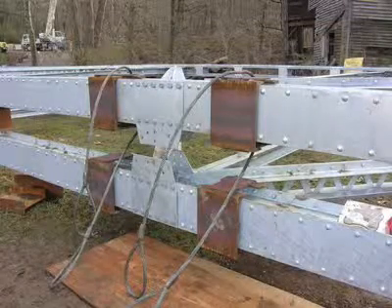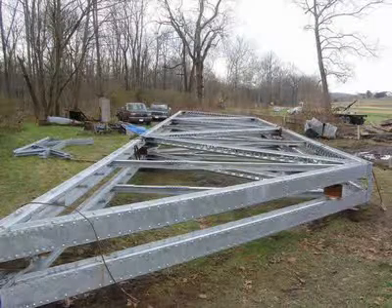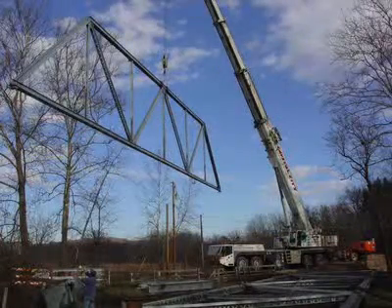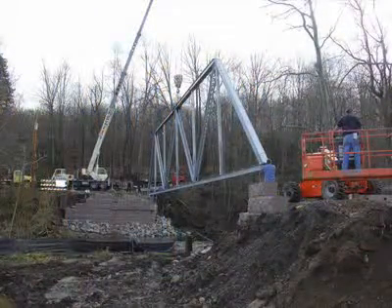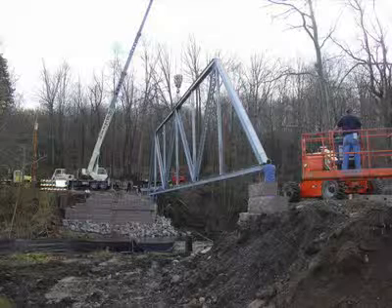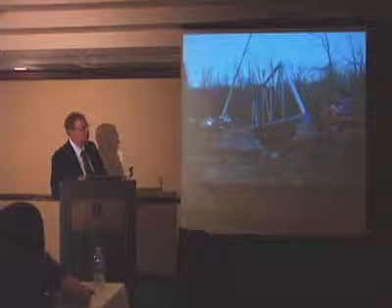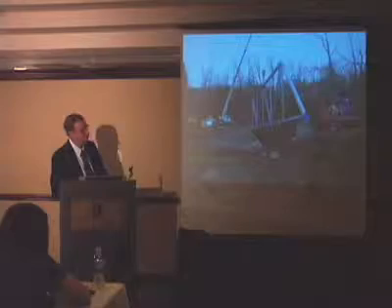The pieces were stacked. Lifting sleeves were built around them to protect the finish from the cables cutting it. And all this was done right near the site. The truss was simply lifted with a crane, swung into place, and set on the abutments, because the abutments were widened and reworked a little bit. This is concrete with form liners, so it made it look like stone abutments. The caps were also done with form liners. The existing abutments were below here.